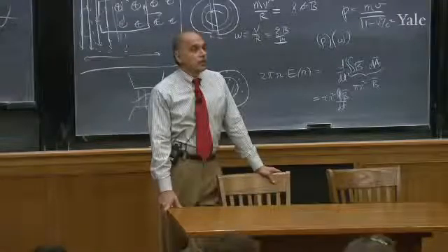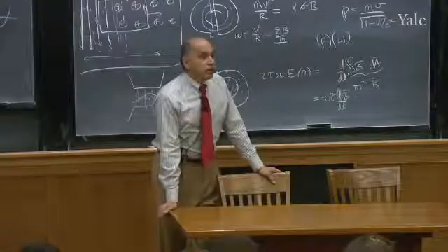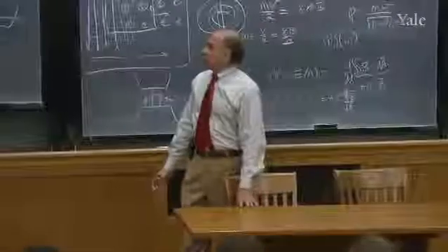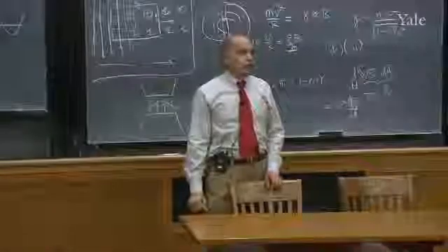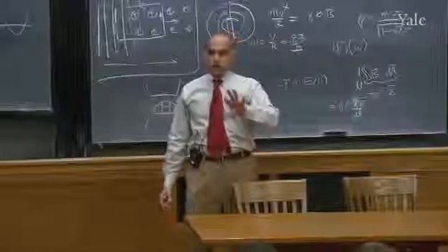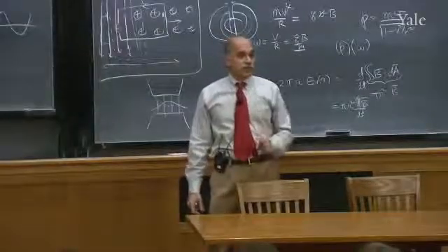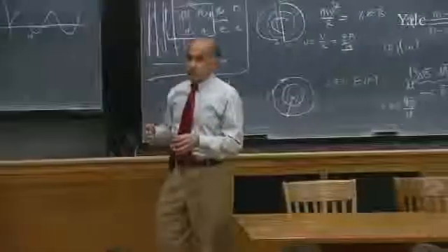The integral of V dQ. Yeah, but I'm saying the total force, you don't have to do any work because there is no current flowing in the coil yet, okay? If there's no current, it's no problem turning a loop in a magnetic field because you don't have the BIL force.